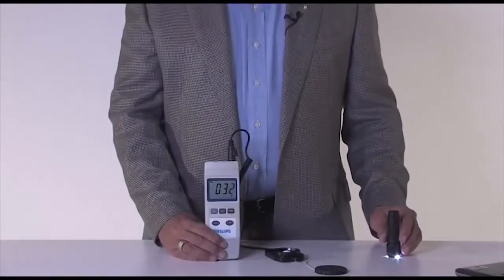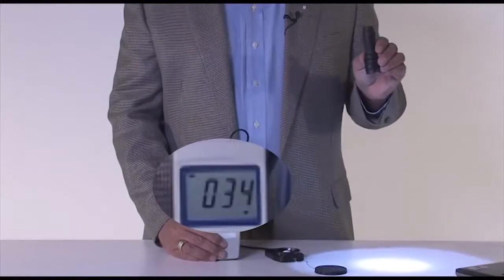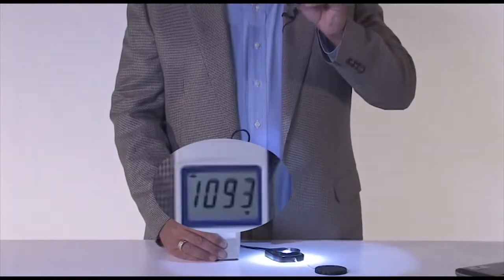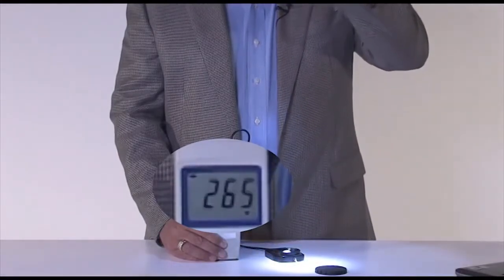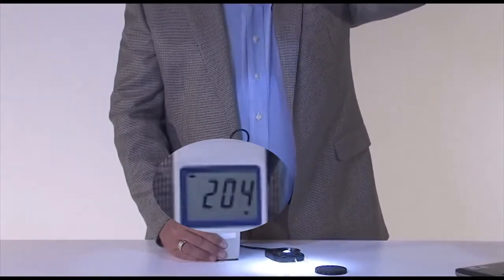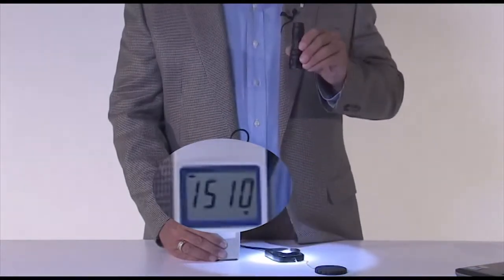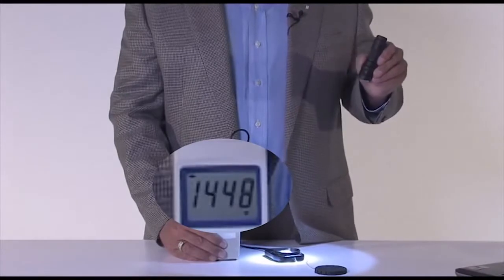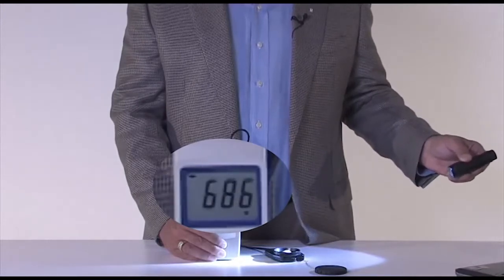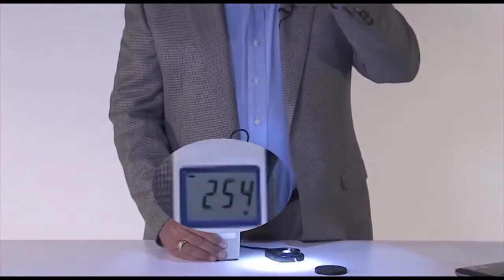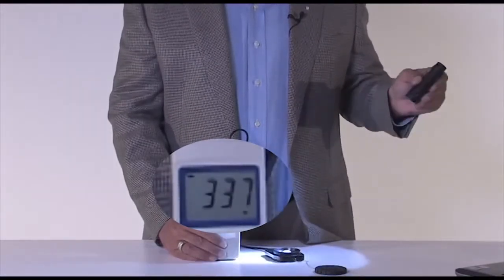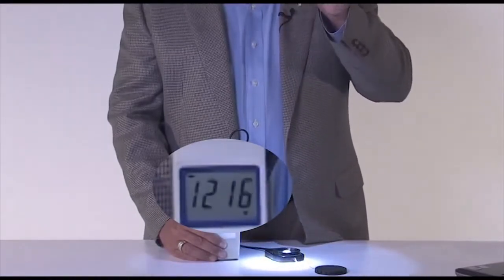So if what we said is true about foot candles, using our light meter and a flashlight, if I hold the flashlight a certain distance from the light meter, I get 1 reading, but as I vary the distance from the meter, the numbers slowly decrease as a function of the distance, reducing the density of light on the foot candle meter. Same too with angle. If I start at a certain angle and I try to keep the distance the same but vary the angle, the numbers also go down. So we understand that foot candles, or the density of light, varies as a function both of distance and also of angle of incidence of light. These 2 things are accounted for in both the equations that we use for determining illuminance.